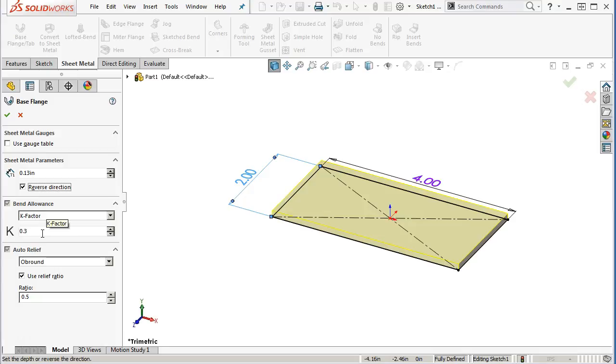All right, so on the other side of things, we have the bend table. We have bend allowances, bend deductions, and bend calculations. Each of those is going to be a table that goes to actual. We took a piece of material, went out and bent it, measured it, got the variation in the initial length to what the bent length was, and we built that into the table for various thicknesses of the material. Ran samples and got usable data out of the mix.